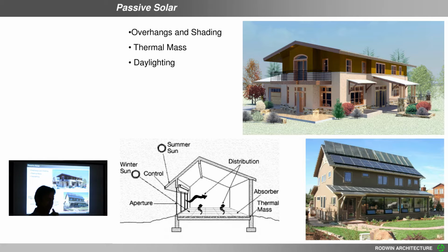If you have a house that has, let's call it a concrete floor with radiant tubing in it, you can absorb a lot more solar radiation than if you have a wood floor with nothing underneath that has a low thermal mass. So just know that with a wood floor, you'd probably want to reduce the size of the windows a little bit, even on the south side. Or you might increase the size of the overhang to decrease the amount of sun that comes into the house because you can't capture it and hold it.